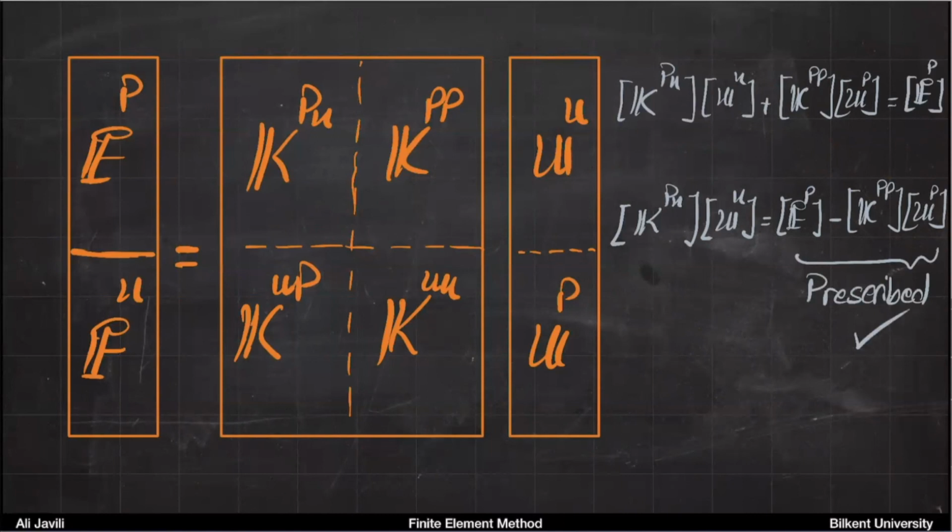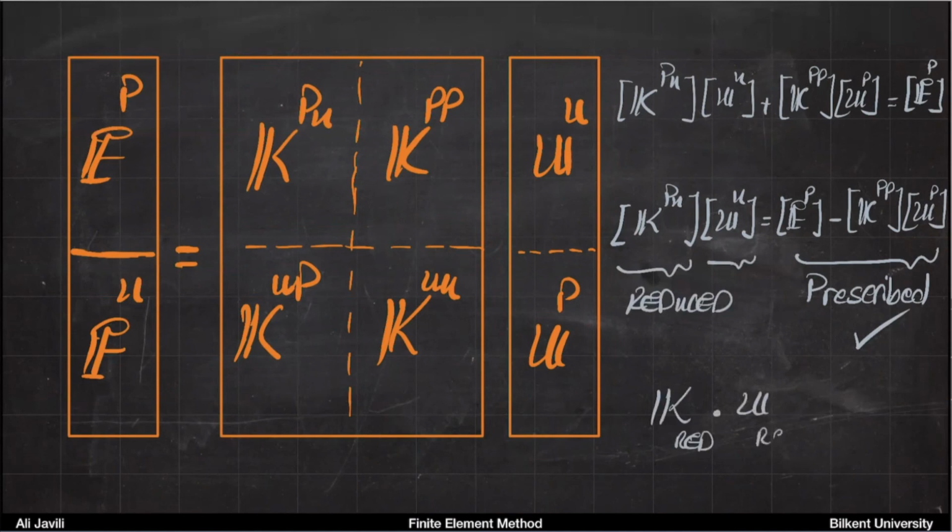And basically, once you know that, what we call the reduced system, then you can write it as something which looks like that. Let's say K reduced. So this is the reduced system. And then you can call this also U reduced. So these are the reduced displacements, or these are only the unknown displacements, equals, and then let's call the right-hand side small letter f. Okay, so that's a vector, that's all prescribed, and from that you can calculate the u's, the unknown displacements.